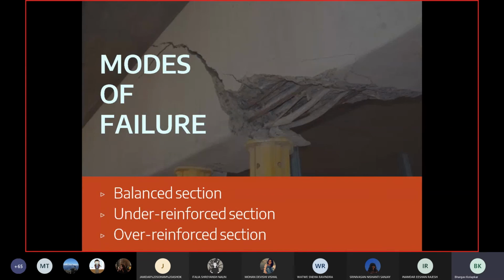So then, like 90% of the time, steel is in a passive state? Under working conditions, the participation of steel is a function of the cracking of concrete. The cracking of concrete is a function of how much stress you are putting on the concrete. So we cannot label it as 90%. It just depends on what it is designed for, what is actually loaded.